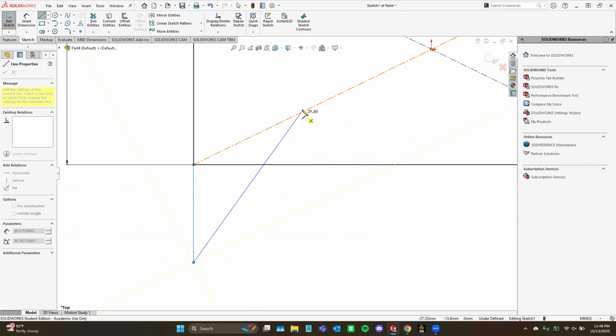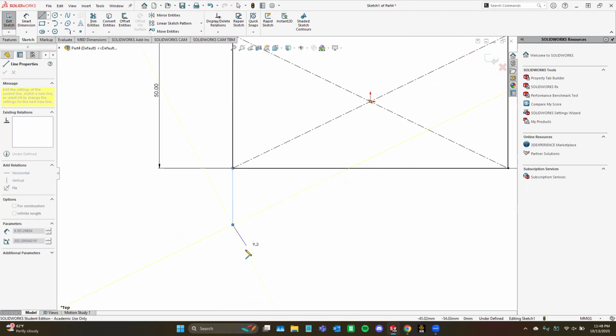It creates that snapping line for you, that guideline. So now it snaps into place and is parallel with the line you just hovered over. And it also provides that perpendicular line as well. So that's a really cool feature to use, and you can just use those guidelines to continue.